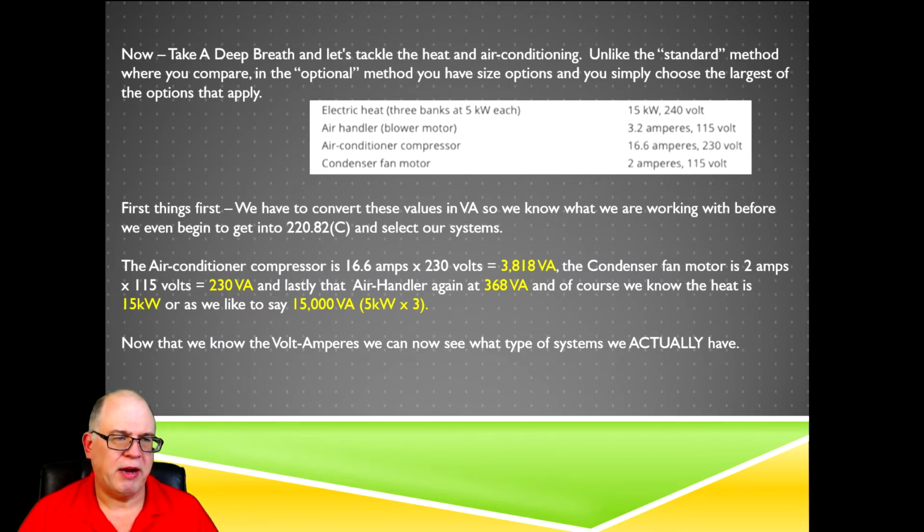If it's horsepower, I have to find out if it's single phase, in this case a single family dwelling. Then I need to go to 430.248 and get the FLC, which is the ampacity, and then I bring it back, and I multiply that value times the voltage, and that's going to give me my VA. In our example here, we've already been given all the amps, and hopefully on your exam you are too, but now you know how to do it. It's not a big deal.